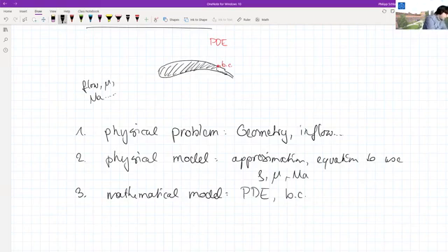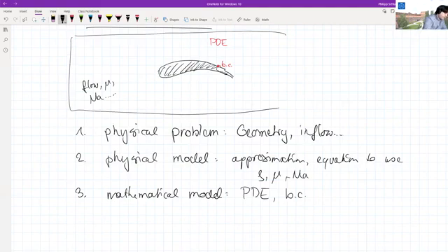I would say, okay, I will actually look at a box, maybe that looks like this, and with my mathematical modeling, I can say that I, for instance, replace the boundary conditions on this side, perhaps with a symmetry boundary condition down here. I would add an outflow boundary condition, a non-reflective condition, or I would have an inflow condition at this side.